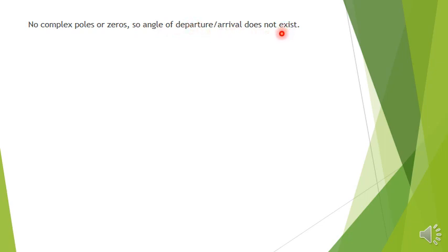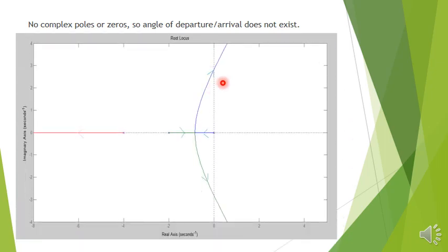So till now, whatever we have calculated, based on that we will plot the graph. After considering all the points, if we plot, we will get the root locus like this, where one branch starts from 0, another starts from minus 2, and at point minus 0.8453 it is a breakaway, and then intersecting at plus j2.828 and minus j2.828. So this is the final root locus.